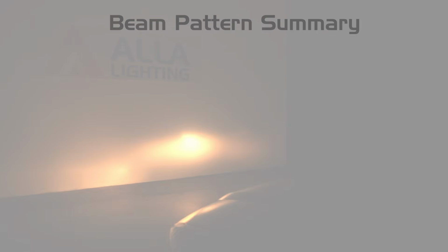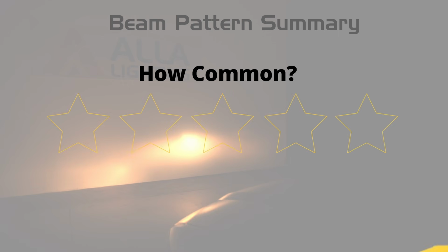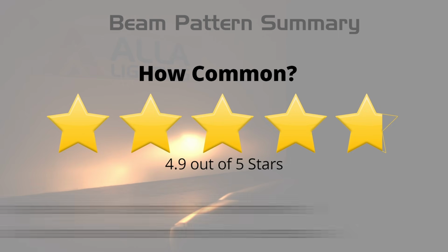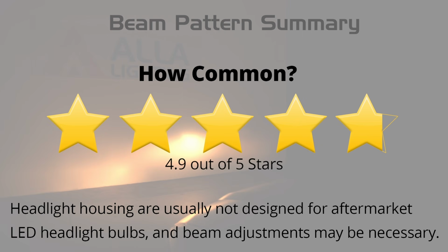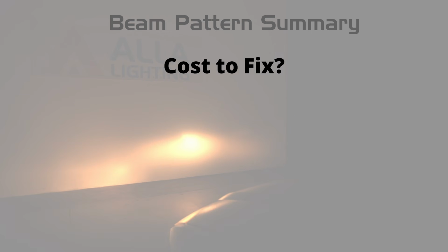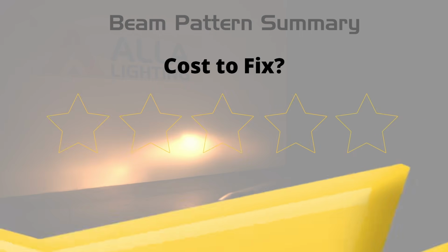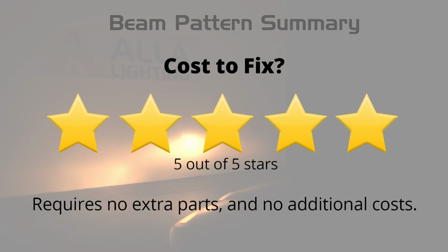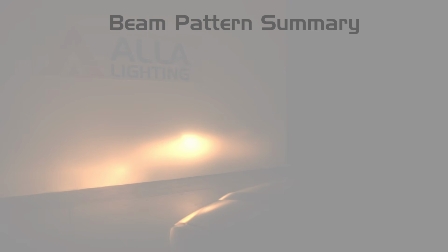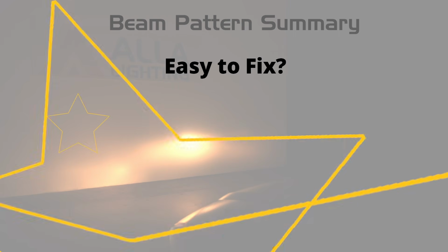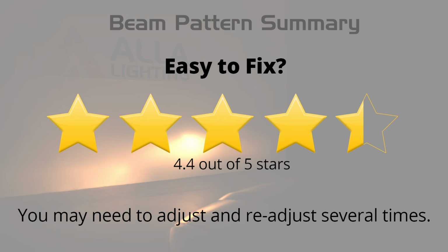Summary. Our first category for how common this issue is rates 4.9 out of 5 stars. Headlight housings are usually not designed for aftermarket LED headlight bulbs, and beam adjustments may be necessary. Next, the cost to fix rates 5 out of 5 stars. This usually does not require any extra parts as long as the bulb is adjustable. And lastly, how easy is it to fix? Rates 4.4 out of 5 stars. You may need to make several adjustments before getting the perfect vertical orientation.